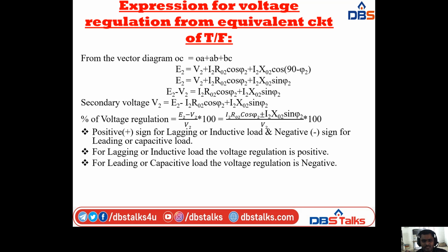So here I am taking the positive sign for lagging or inductive load and the negative sign for capacitive or leading power factor. So for lagging or inductive load, the voltage regulation is positive, and for leading or capacitive load, the voltage regulation is negative. So this is the expression for voltage regulation.